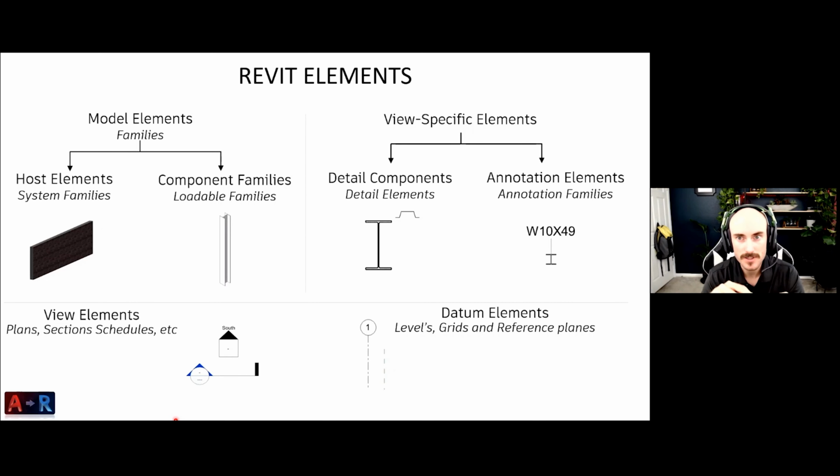Levels also get reference to different views that we're at, so floor plans, sections, all of those good items. We also have reference planes that help us design in our design environment as we go through. Maybe we need to reference something or just get a rough sketch of something, we can place our reference planes as we're going through in our design environment. But those are our Revit elements.